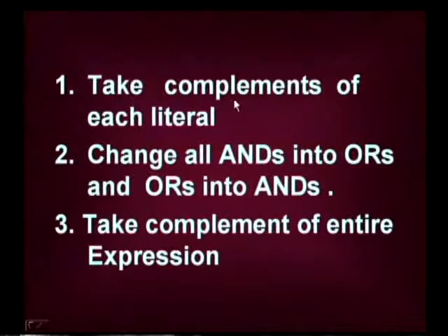The 3 steps you have to follow are: take the complement of each literal, then change all ANDs into ORs and vice versa, that is, all ORs are to be changed into ANDs. Then take the complement of the entire expression. Following these 3 steps, it is possible to see that a given expression's output will not change even if the nature of the expression is changed.